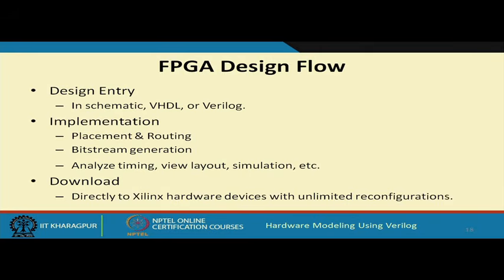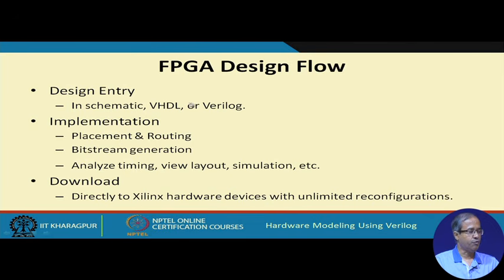Okay, fine. So, FPGA design flow, if you just look at it, consists of design entry to start with, you can do it in Verilog. Then the software that is provided by the vendor, like I talked about Xilinx ISE or Vivado, they do placement and routing, partitioning, but here it is different. Here partitioning means partition into sub circuits with maximum 4 inputs and 1 output, because each partition I will be mapping to one of the LUTs, and these LUTs will be placed into one of the CLBs, configurable logic blocks.